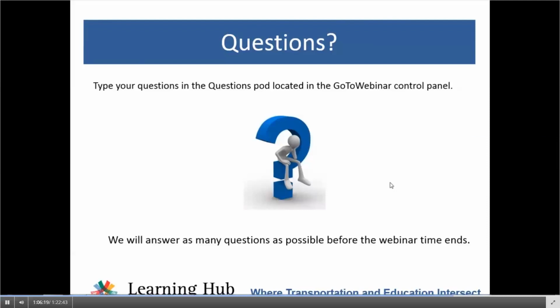Great. For the BRT analysis, is ridership a consideration, or person trips a consideration, in the evaluation? Well, the HCM is not a demand estimation model or tool, so we really don't get into ridership or person trips. It would certainly be something that you could look at in addition to the operations. You could look at how ridership might change with respect to the improved speed on the facility, for example.